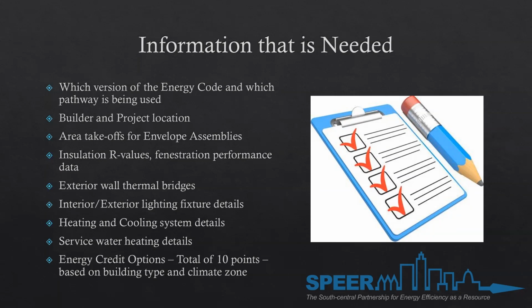That's something that's been overlooked a lot with just doing modeling. Now you have to have fan efficacy. The fan has to be efficient. It can't just be a low CFM fan with high watt draw. It has to meet fan efficacy tables. The new version of the web ComCheck actually checks that, and it tells you that you're either good or you're not good, or that a horsepower motor of this size needs to have this much efficiency, and it walks you through and guides you through how you're going to do that.